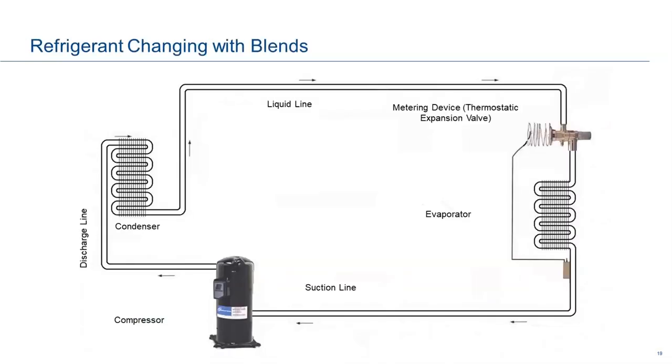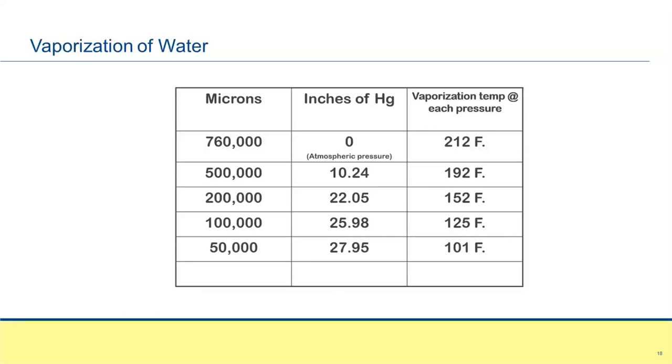So if we go back here, at 500 microns, it's not going to pull up for me. We're close to 30 on our gauges. We're boiling water at -12, okay, over here. And that's what we want to be at, 500 microns, okay? We're boiling water at -12.